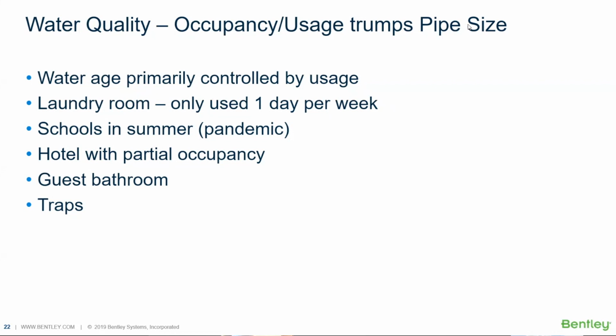Well, it's because the traps dried out. If you have a long enough period with no water use, the traps dry out. And if you have the right meteorological conditions, that just sucks sewer gases from the sewers up into your building. And so these things where you don't have water use become pretty interesting.